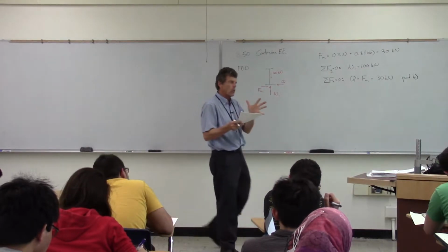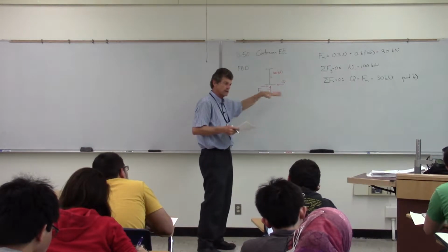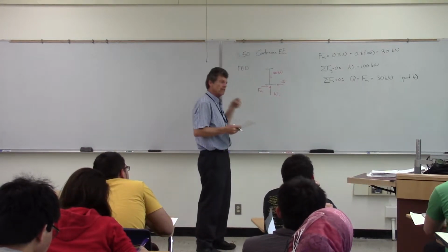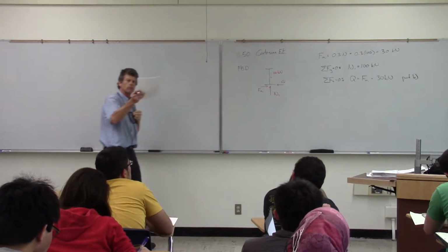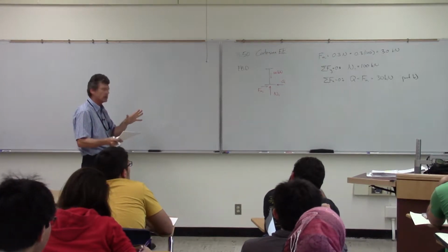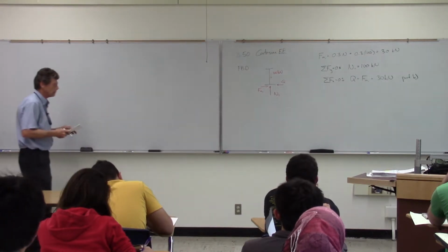But because it is a wedge and it's a machine, what we want to do is push that wedge in there, so we need to calculate what value we need to figure out what that P is to push that thing through. So that's a good point, that we want to take it to the maximum. That's why I say most of the time we're doing it, it's going to be that case 3. We're taking it right up to the impending motion.